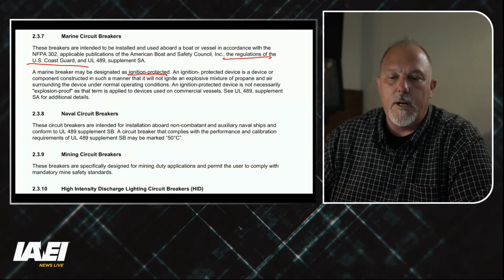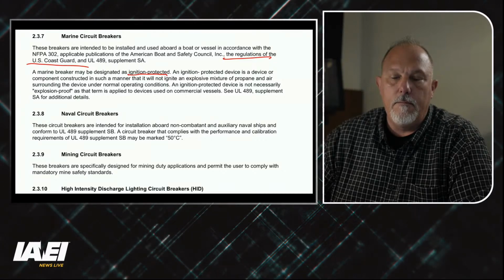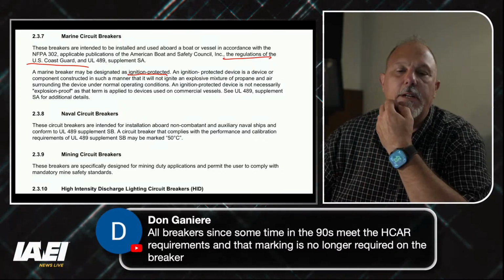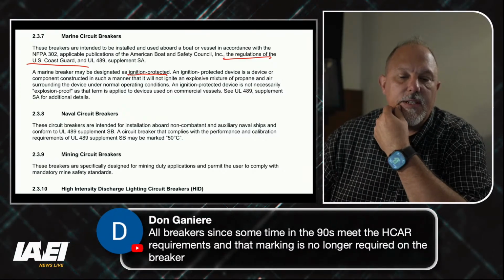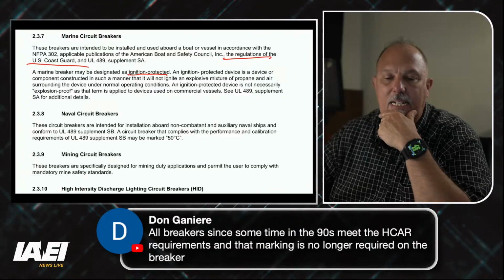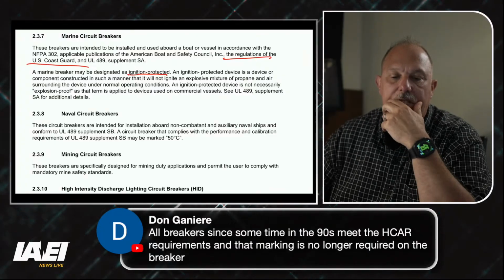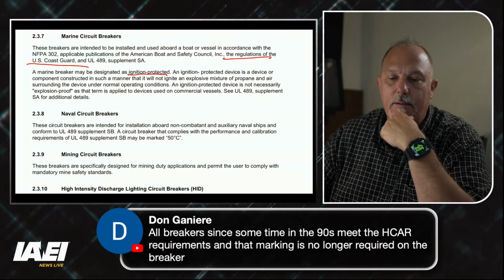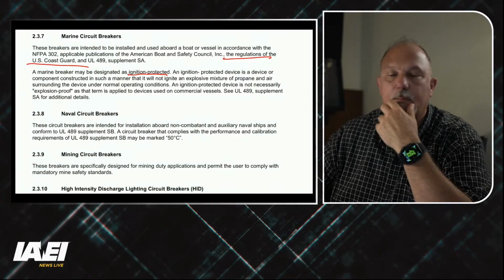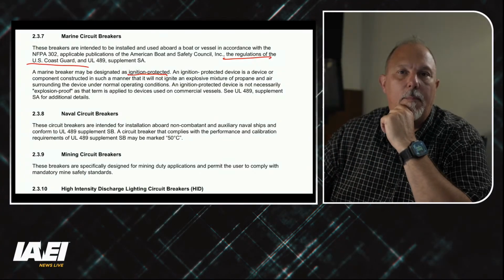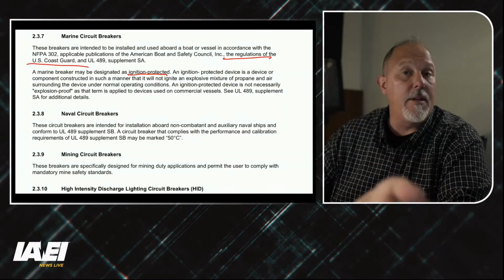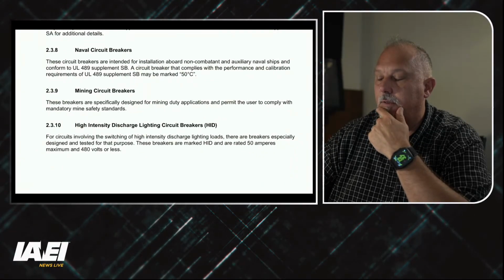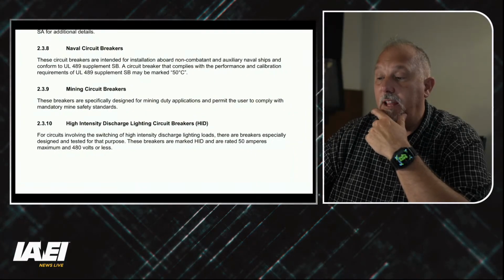I'm not going to spend too much time on it. Don, I was just reading Don Ganier's note. Don says, all breakers since sometime in the 90s meet the HACR requirements. I agree with you, Don. I think it's just part of the standard. I'd have to take a look back at the UL standard. I believe every one of these devices are adequate for that. Then you have your naval circuit breakers.